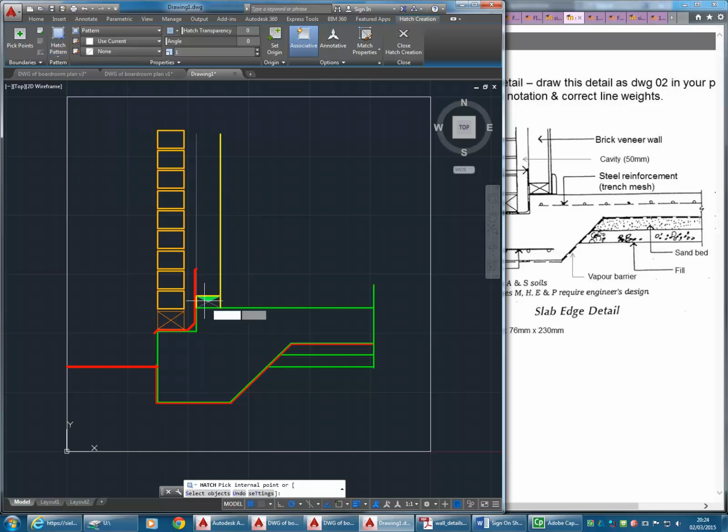And then I'm not going to place it, I'm just going to hover over this so you can see the size. And you should always look at that. With this new preview mode, it's a really useful option. And that's actually turned out pretty well. But that's a bit of a fluke. So it's really because we're doing a detail and we can get away with a scale of 1. But in most cases that's not going to work.